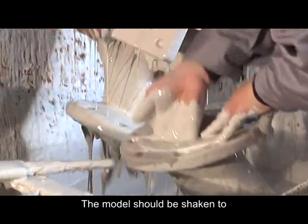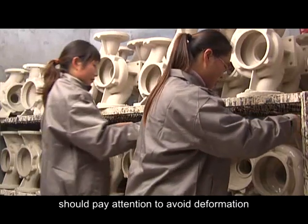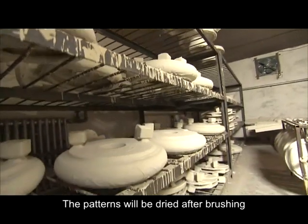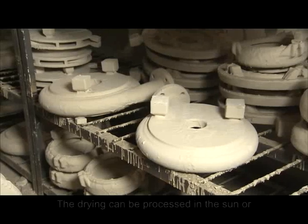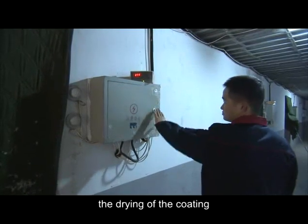The model should be shaken to remove excess coating. The delivery and placement of the patterns should pay attention to avoid deformation. The patterns will be dried after brushing. The drying can be done in the sun or in a drying room at 45 to 50 degrees Celsius to accelerate the drying of the coating.